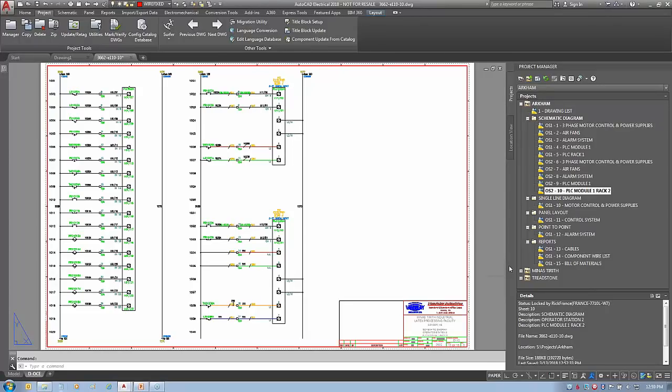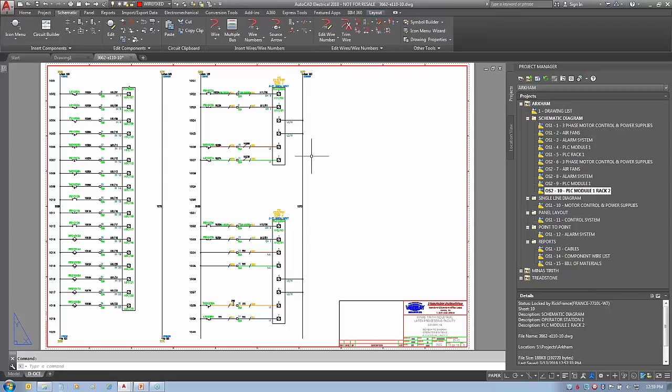First thing I want to do, well, actually we're ready to update the title block, but I'm going to use a different command. I love update retag right here. It's on the project manager, it's on the project tab. With update retag, I'm going to go to here, schematic. Notice one thing here, my sheet numbers. I need to fix those. Now I can fix that with the title block update. Fixing those